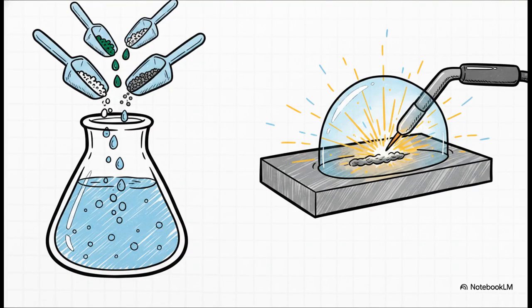Now, unlike carbon steel, which focuses heavily on those tensile strength grades we just analyzed, stainless steel plates are categorized entirely differently. You're going to see codes like 304, 304L, 316, and 316L. These numbers don't represent strength. They represent chemical composition variations. You're essentially changing the chemical recipe. For instance, moving from 304 to 316 usually involves adding an element called molybdenum to drastically increase resistance to certain types of severe chemical corrosion. And that L? That stands for low carbon, which is absolutely crucial for preventing corrosion during the welding process. So as you can see, it's a totally different paradigm of material selection.